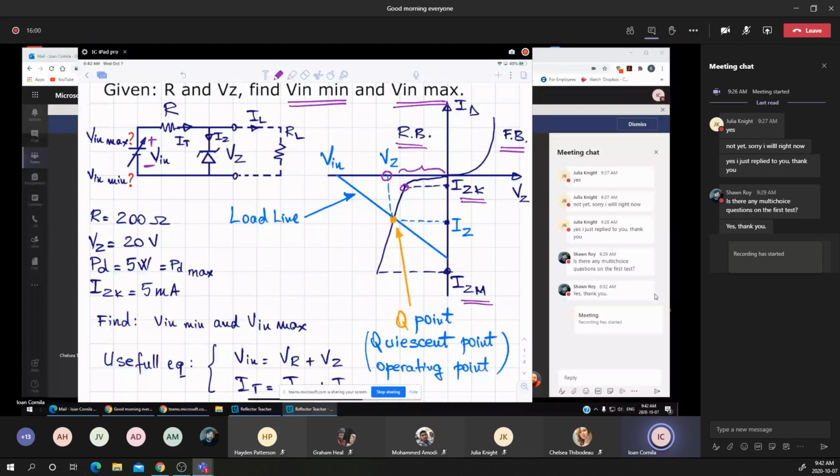We make the assumption that if Vin is less than VZ, the diode acts as an off state, or a switch turned off, which means there is no current. We did this experiment and figured out that the current in this region, if the diode is in reverse bias, is very small and negligible in our calculations.